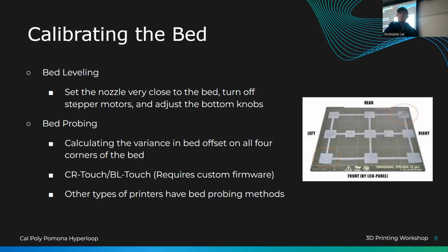But it's essentially just a system where you know the absolute distance between the actual nozzle and the touch probe. That goes through and tests it and then understands where it is, basically. That's the cool way to do it. That's the much easier way to do it, because you only really need to mess with it once, and then you're done.